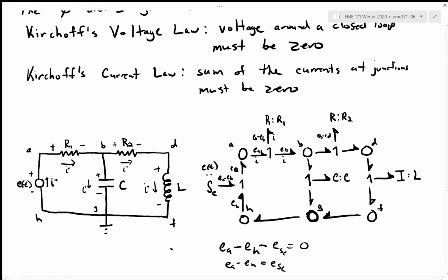I have here established all my zero junctions, and then for each component I have these voltage drops associated with the one junctions. I've written my ports, labeled them, and made sure my sign conventions are correct with my half arrows and that things add up as expected.